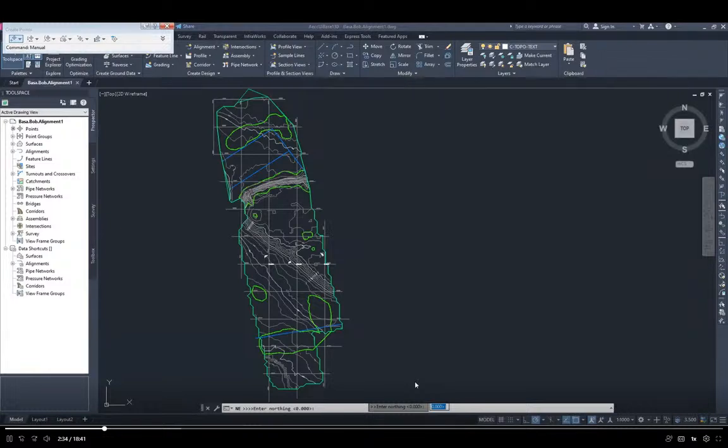First, I enter my northing for my A point. Oh, not entering in here. Sorry about that. There we go. I hit enter. It's asking me for my easting. Now it's asking for a label, a point description. This is point A. I'm going to enter in A and hit enter. And then for a point elevation, we're not going to enter anything in. The default is a period. That's fine. You're just going to hit enter here. Okay, and there's our first point.